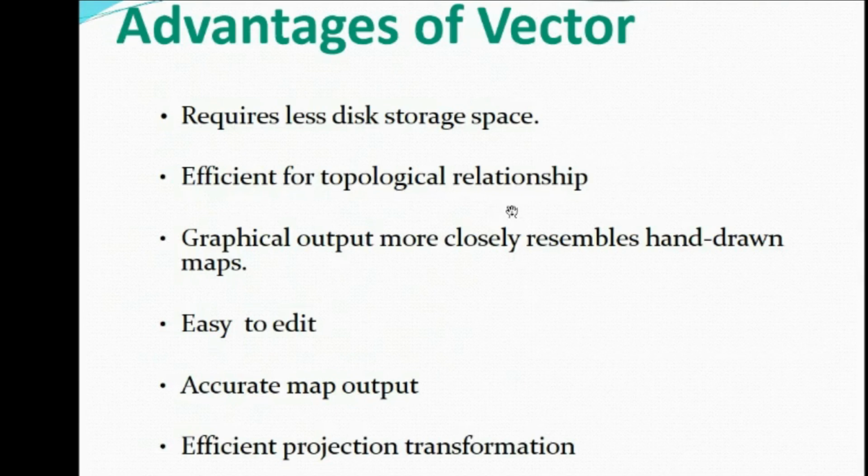For example, if there is a duplication or repetition of the data, or if any connectivity is missing between road network lines or some other feature, these inaccuracies can be cleared, and the removal of duplication or missing lines can be done through the topological study or topological tool usage in GIS.